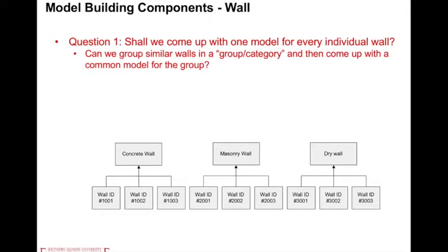They use different materials, but all these walls belong to the wall class. So instead of representing all of these different walls separately, we will use one parameter, material, to cover all of them, because material is the abstract concept. You can fill in concrete, masonry, dry wall, and wood materials into this parameter.